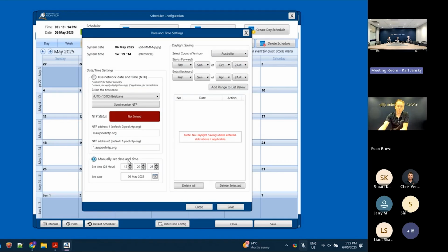It is important that you set this up, and there's two mechanisms to do that. There is manually setting up the date and time. There is a real-time clock within the product, and that will keep the date and time running within the product. If you power cycle the product and turn it off for approximately 1 week's time, you need to reset it, as basically the internal power supply has died by that point. So if you're using manual setup, please keep the unit on and don't turn it off for long periods of time where you'll need to reset it.